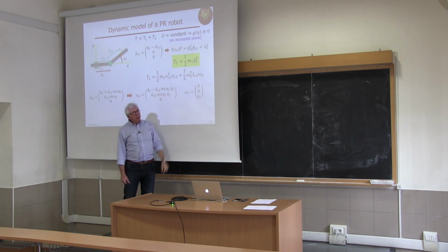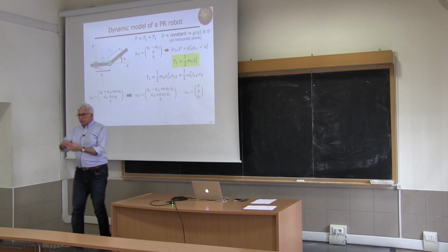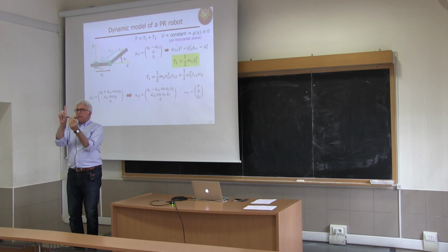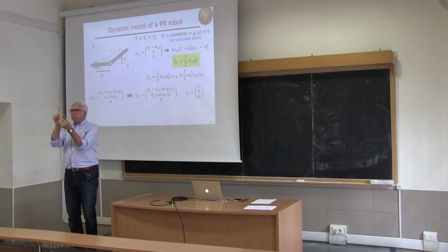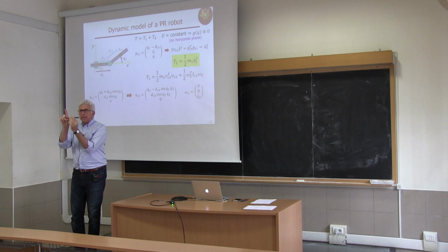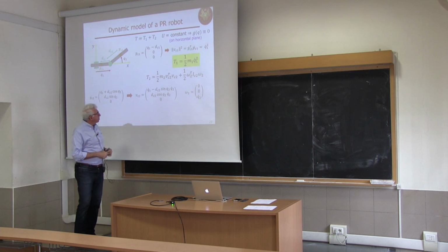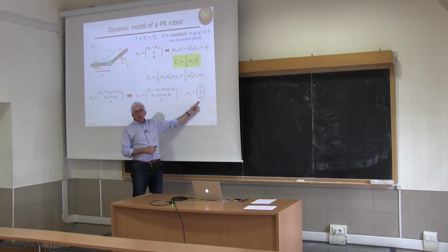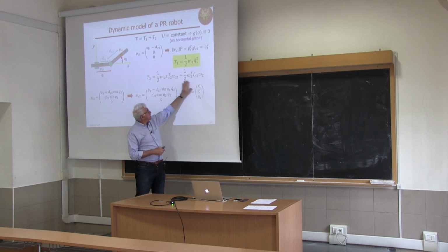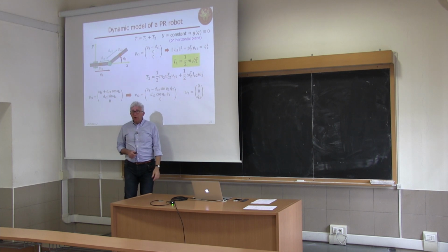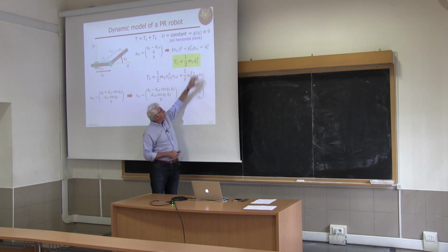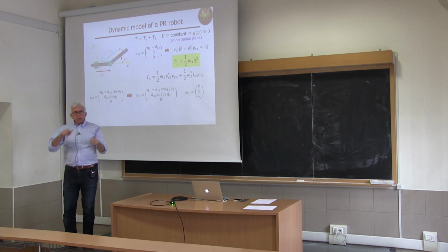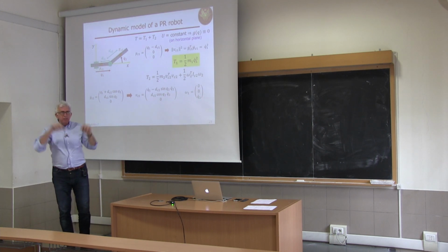While for the angular velocity of this body on the plane, its only rotational velocity is a vector around the normal to the plane of motion. And its intensity is exactly the intensity of the joint velocity 2. So the vector omega 2 is 0, 0, q2 dot, which means that if you put this into this quadratic form, and you have a 3 by 3 inertia matrix of the second link, you're only interested in one component of this 3 by 3 matrix.